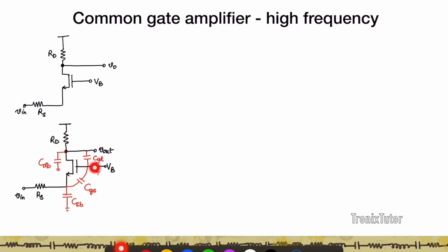So in this common gate configuration, there is no capacitance connected between the input and the output, primarily because in the common gate we connect the input and output to the source and drain of the transistor, and in a MOSFET the source and drain are assumed to be intrinsically electrically disconnected. If there was a capacitance between source and drain, we would have DIBL. The whole point of an ideal transistor is you want to ensure that the drain voltage does not affect the source voltage. And so you don't have a capacitance connected between input and output, which means the Miller effect doesn't work here.